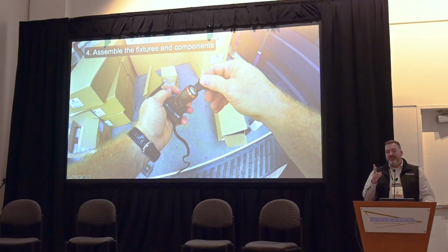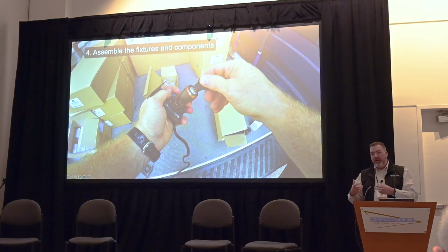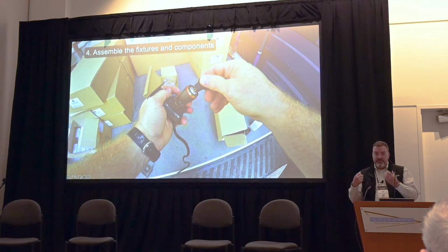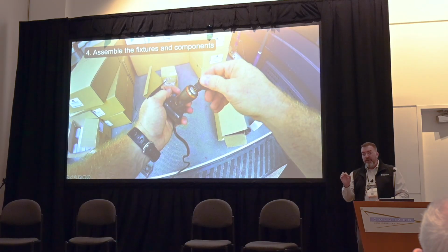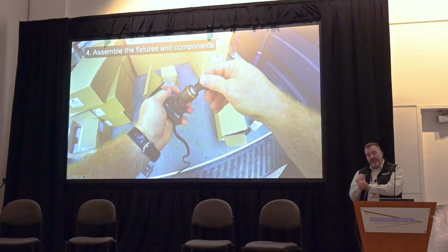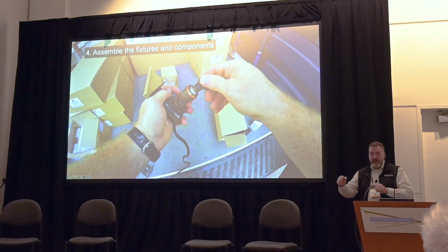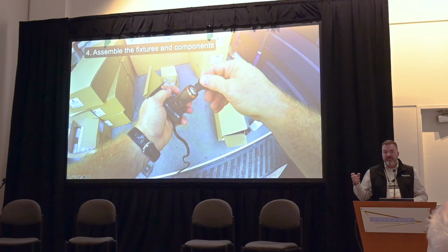Okay, so Tech 2, while Tech 1 is installing the transformer, for efficiency, what I do is I break up Tech 2. His job is to start, if you haven't pre-assembled your fixtures, get them out there, open those boxes up, get all your fixtures pre-assembled, get them lamped or get the modules on, get the accessories on, lay them out in the grass. Good rule of thumb, if you haven't installed them, leave the plastic on, because as you put those things in the landscape, you're going to be working around them, you're going to bang them, they're going to get dirty, you're going to have to pick them up and move them with dirty hands. It makes for less cleanup later. So if you can leave a little bit of plastic on those bodies, it helps, or just plan to go and wipe them down at the end.